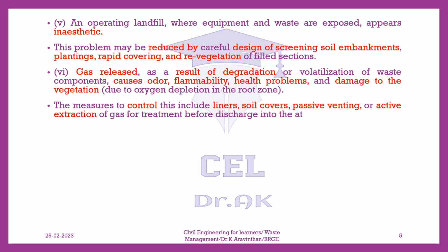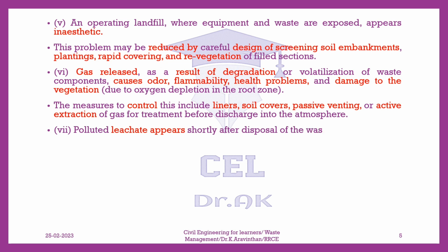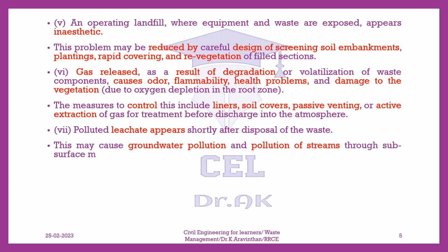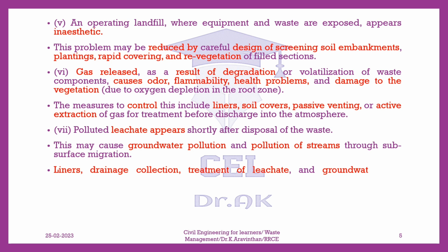7. Polluted leachate appears shortly after disposal of the waste. This may cause groundwater pollution and pollution of streams through subsurface migration. Liners, drainage collection, treatment of leachate, and groundwater and downstream water quality monitoring are necessary to control this problem.